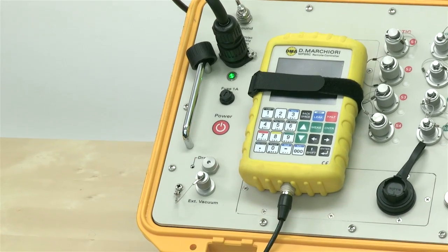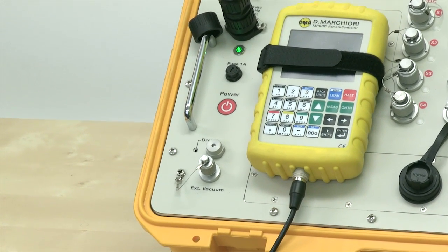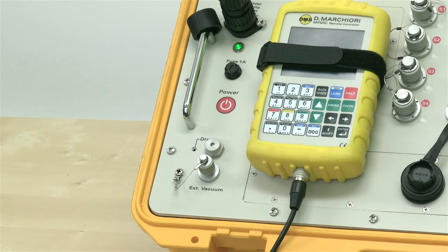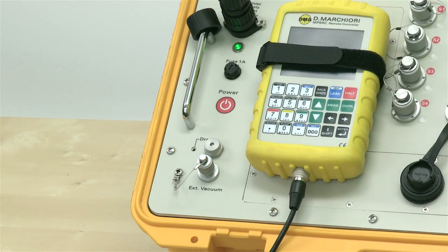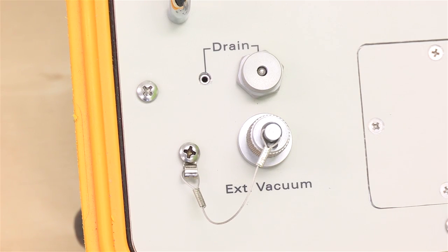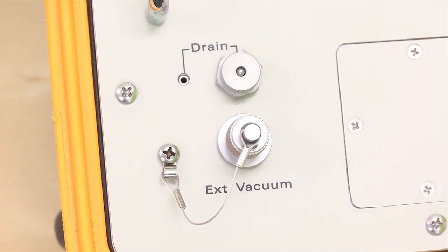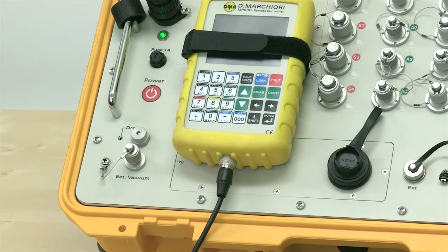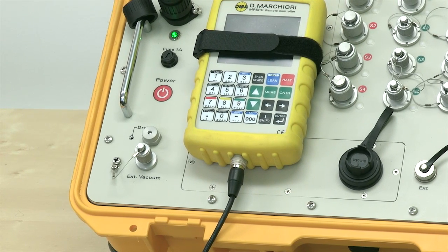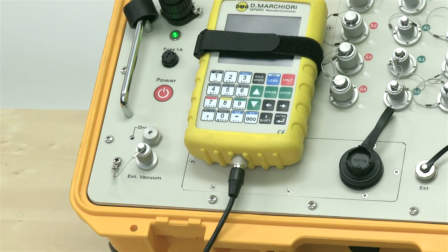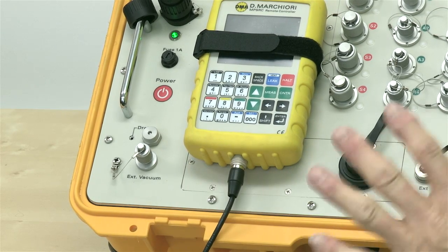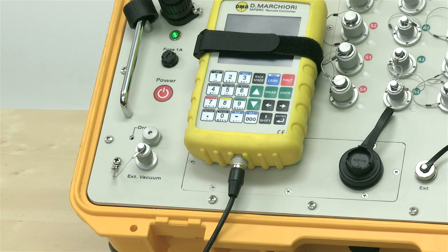Coming down here, we have the ability to drain the instrument should we get condensation within the instrument. By pressing the center point there, it will actually blow out of the system any drops of condensation which have perhaps entered the instrument. Down in this corner, we have an external vacuum. That is because we also manufacture a range of pitot-static adapters, and one feature of the static adapters is that we use hold-down rubber cups, and this is the vacuum which would press the adapter close onto the fuselage of the aircraft.